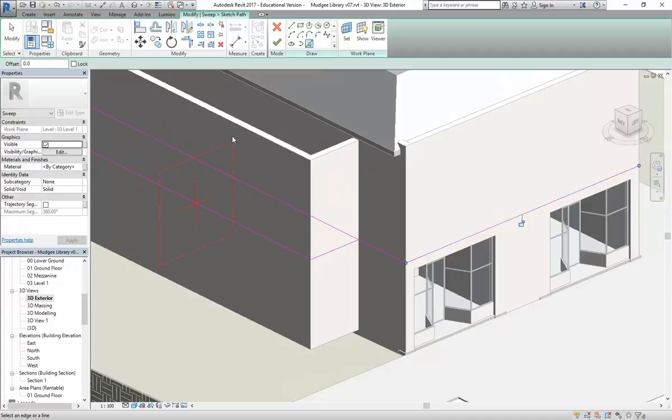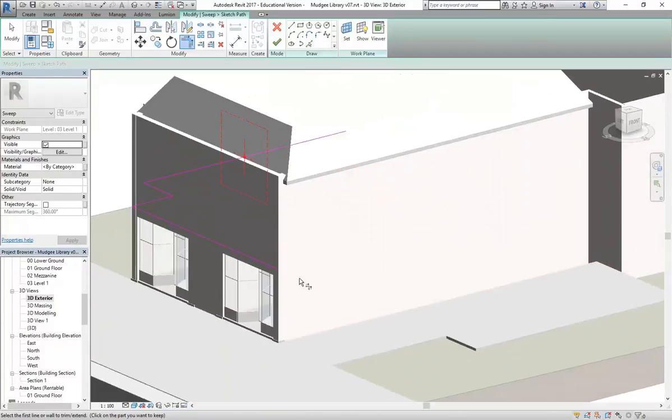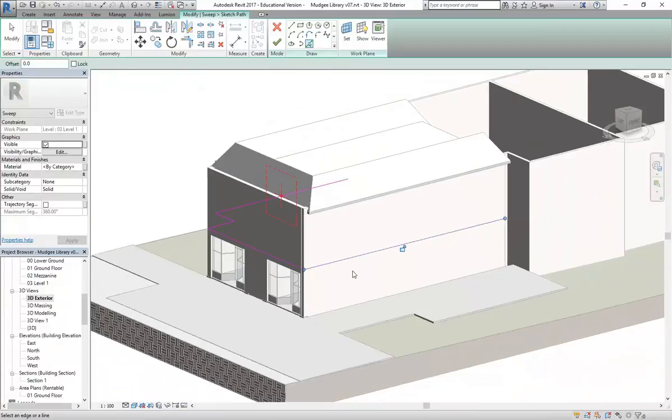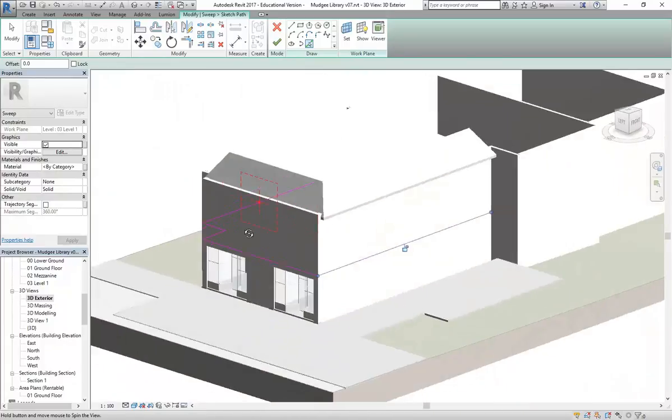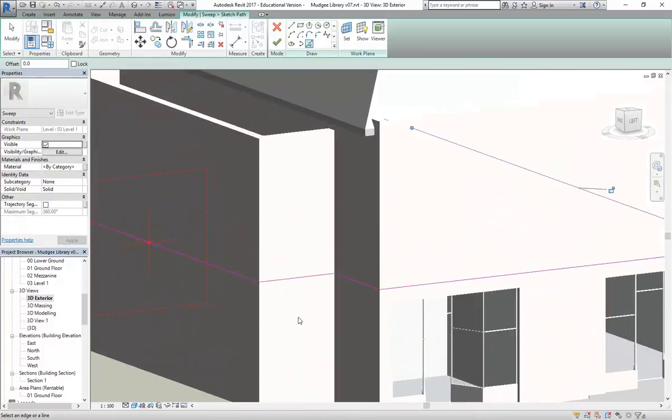This is one of the best things about Revit, actually, the fact that it automatically projects. It's done this from day one. So it projects onto your work plane, which is a really, really useful feature. So I'm not going to go overboard here. I'm just going to do what I need for the front, and I can extend it later. Okay, so that's done. Tick to finish.